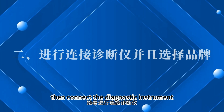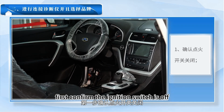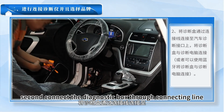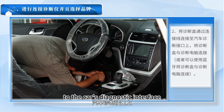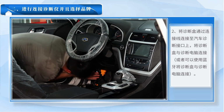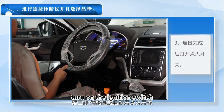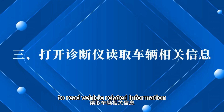Then connect the diagnostic instrument and select the brand. First, confirm the ignition switch is off. Second, connect the diagnostic box through the connecting line to the car's diagnostic interface. Connect the diagnostic box to the diagnostic computer. After the connection is completed, turn on the ignition switch. Turn on the diagnostic tool to read vehicle-related information.